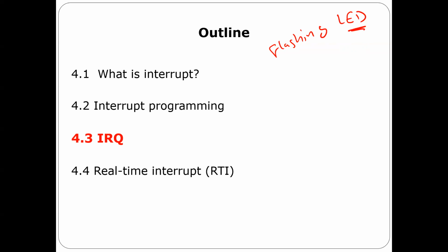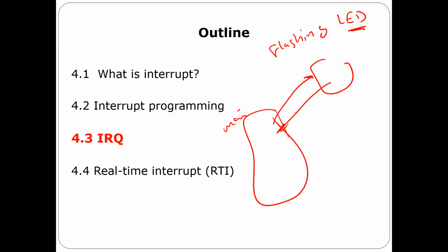However, a general advice: you should do your best to reduce the amount of code in any interrupt subroutine. Why? If this is the main program and I want the microcontroller to go execute a subroutine and come back quickly, any delay or extra time here will impact the performance of the whole system.